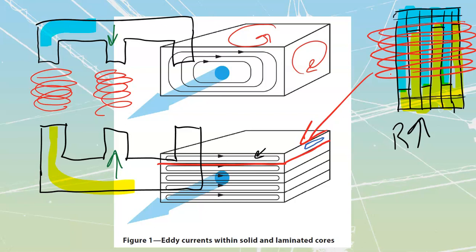If they want an even better type of transformer winding encapsulation, they're going to take your entire transformer and vacuum out the inside. So it'll be inside of a sealed canister. They're going to stick the low end into epoxy. They're going to attach a massive vacuum pump to the other side, and they're going to pull the epoxy all the way through. This removes all air bubbles so we don't deal with problems like corona and things like that inside of there. And it's also going to fill it up with that epoxy, which is then able to harden.